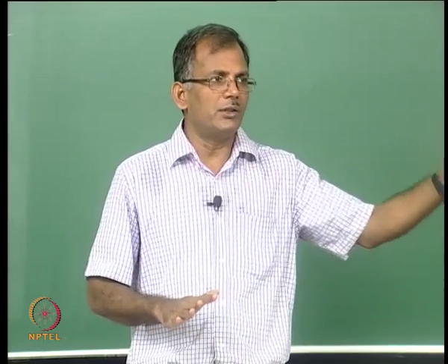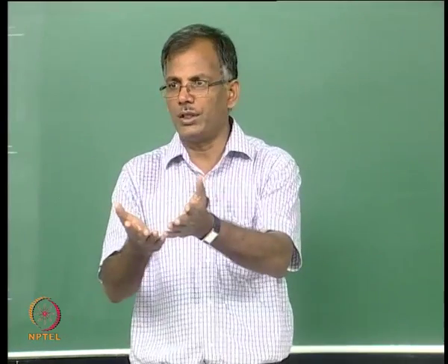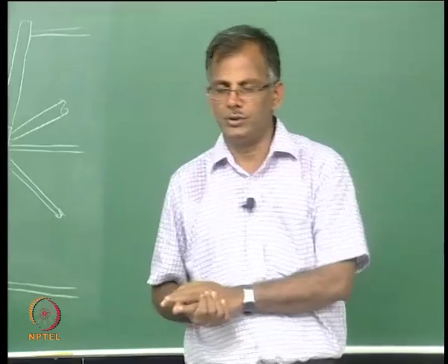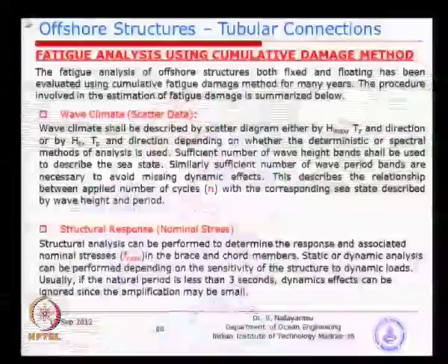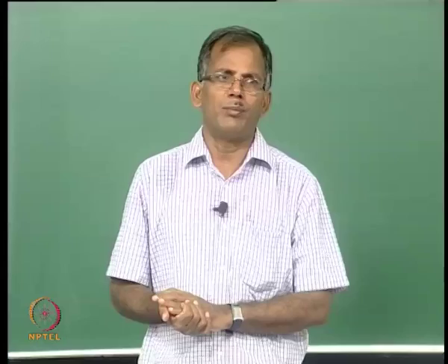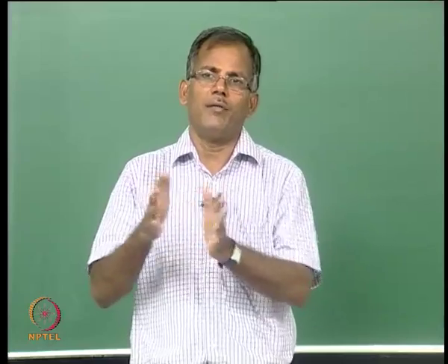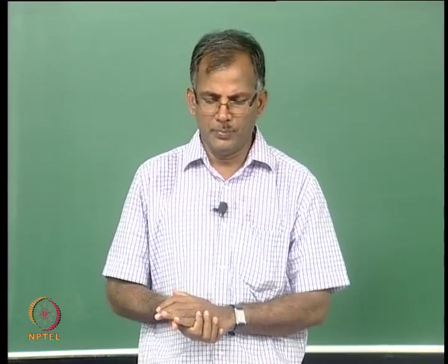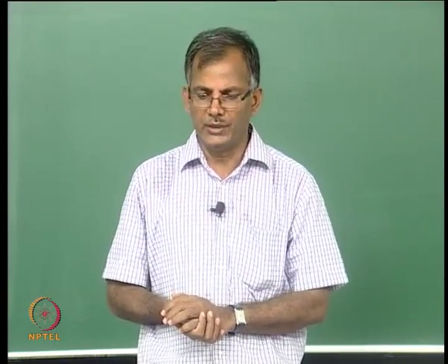As long as you know what is the sea state, you apply the loads to the structure, you get the response. Now, for the structural response, you could include or neglect the dynamic effects depending on whether the structure is close to the natural period, close to the wave periods. That I think is a secondary matter, but most of the jacket structures are away from the natural periods close to the sea state conditions.